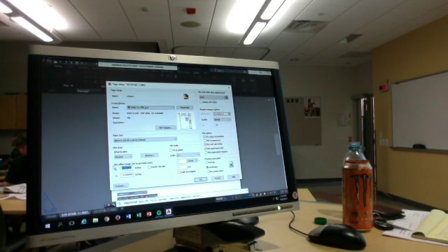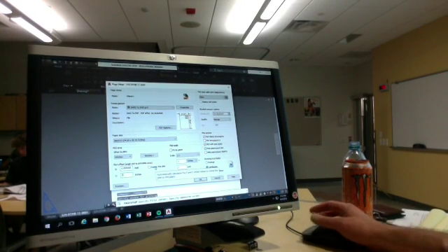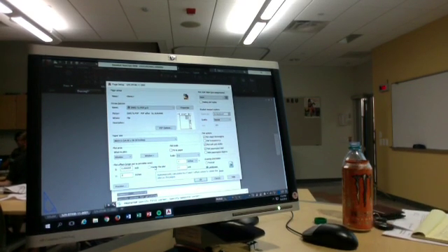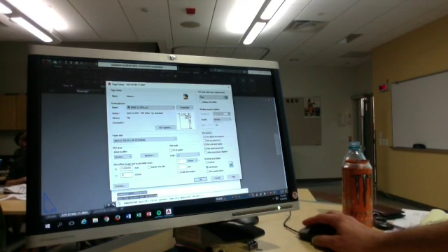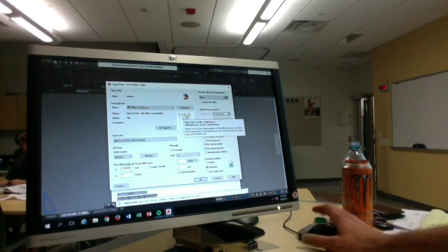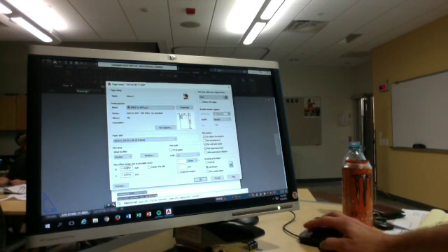Typically I always center the plot at where I work, but sometimes you will want to offset the plot a little bit because a lot of companies will still print drawings, and you'll want a little margin on this side. That margin gives you the ability to staple them all together. Or let's say you're printing it for an 11 by 17 binder or an 8.5 by 11 binder. It gives you a margin to put your 3-hole punch in and actually put it in there. So like I said, I usually center the plot at where I work.